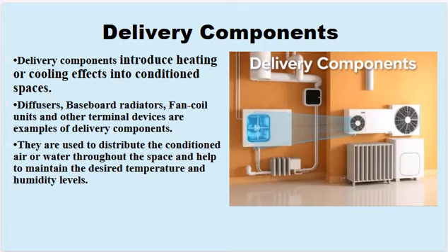Valves are another important part. They regulate the flow of hot water or steam, adjusting temperature as necessary. We also rely on fans to push air through the ducts and ensure even distribution of warm or cool air into the space. Dampers are used to control the airflow within these ducts, allowing precise temperature and airflow adjustments. Together, all these components maintain a consistent and comfortable indoor environment by delivering the right amount of heating or cooling to every space.